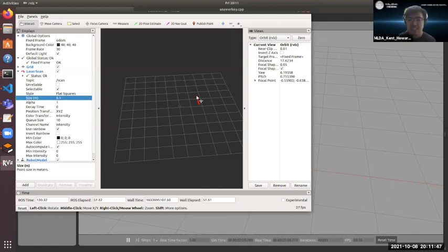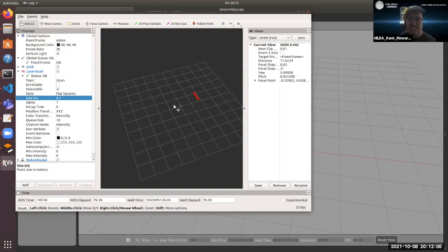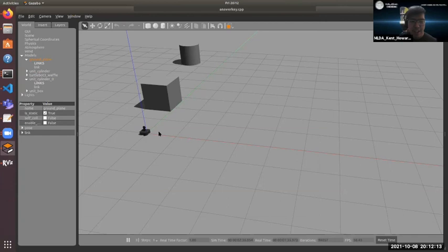You see the lines here. So if there's only one box here, then of course if we detect something, it's that thing, if there's nothing else there. So what I do simply is, for my code, I plan to take in the minimum distance. For example, I'm facing this direction now, and based on my laser scan, I want to take the angle of the minimum distance, which is this angle right here.